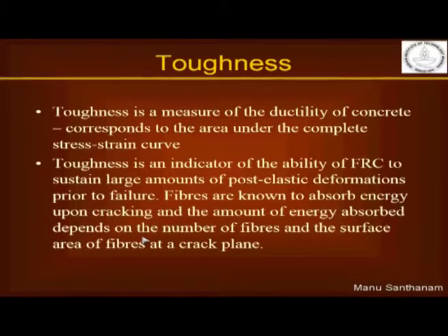Okay. So, I was talking about the fact that you can use this information from the post peak behavior to calculate some important characteristics of the concrete, like the ductility. Now, a very important characteristic within this ductility is the toughness of the concrete. Toughness is a measure of the ductility and it corresponds to the area under the complete stress strain curve.